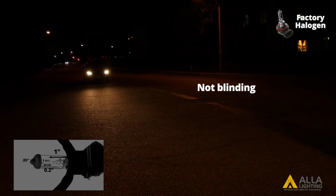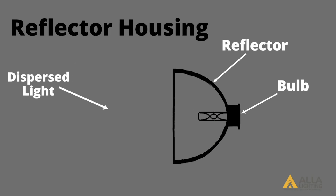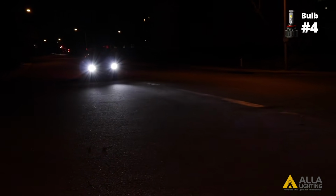There's no doubt stock incandescent bulbs that come installed in your vehicle are too dim to improve night driving, and they do not have such blinding issues. The reason that they do not blind people is not because they are too dim, but the headlamp housings were carefully designed and tested to work with those stock incandescent bulbs by optical engineers. In the same way, some LED headlight bulbs causing blinding issues are not because they're too bright, it's because they have a very poor beam pattern.